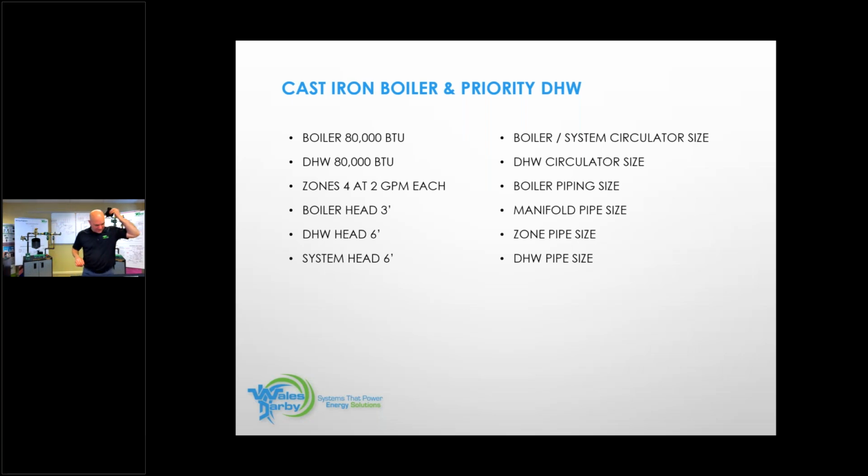Okay. Good morning, everybody. So we left off last week, and we left you with a couple of problems, as if you were moved into a service manager type role. You have a technician in the field, he's calling you and giving you all this information. So it's an 80,000 BTU boiler. The indirect has the ability to absorb 80,000 BTU. It's a cast iron system with priority hot water. So we'll do that through the TACO relay. We've got zones, 4 zones. They're 2 gallon per minute each.